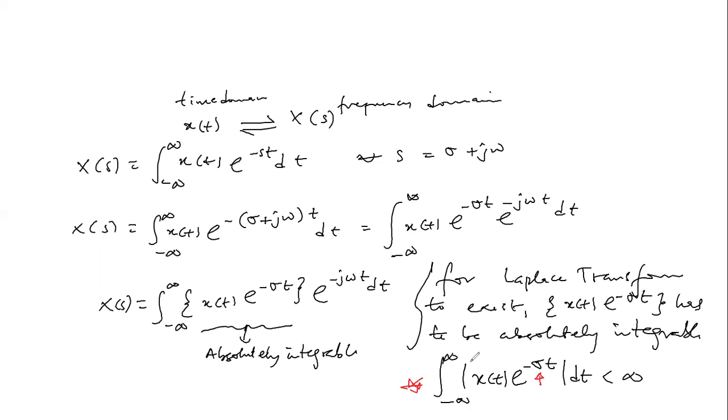Now, this is the interesting part when playing with the Laplace transform. So I really need you to take note right now. We've been able to decompose the Laplace transform such that we have separated the exponential function that is dependent on the damping factor and the exponential function that is dependent on the frequency. Now we are saying that the signal multiplied by the exponential function that is dependent on the damping factor has to be absolutely integrable.